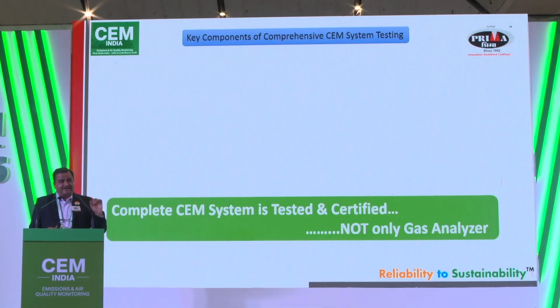The certification is not only for the analyzer, which may be just a part of it. When you say CEMS, I call it Continuous Emission Monitoring System. I never say Continuous Emission Monitoring Analyzer. So when it's called CEM certification, that means it is a complete system, starting from your probe, gas sampling system, conditioning device, controllers, analyzers, your PLCs, HMIs, and your software also has to be part of the certification, and your data transmission has to be part of the certification program.